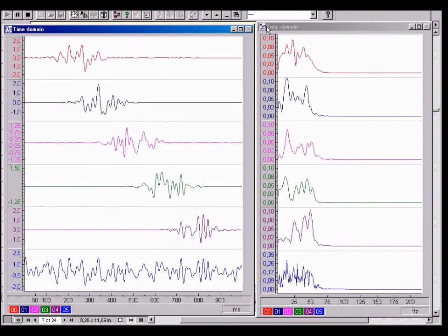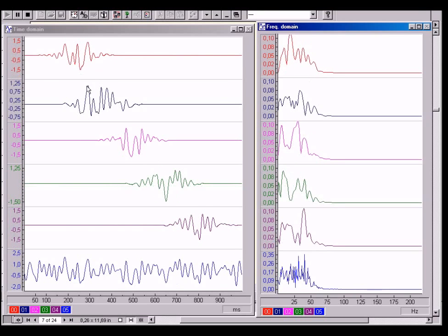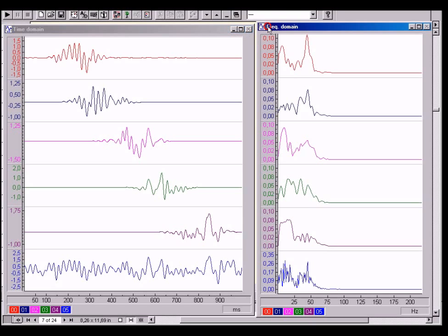The long non-periodic signal here is also divided up into individual time segments. This so-called windowing is carried out by means of a time-shifted Gauss window. The partial segments thus begin and end gently. In contrast to the previous illustration, the frequency domain of the time segments is not greater than the frequency domain of the signal as a whole. This important signal technology process in the time domain is called windowing. This is intended to define cutting out in the frequency domain, which is called filtering.